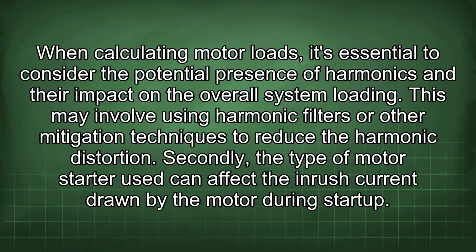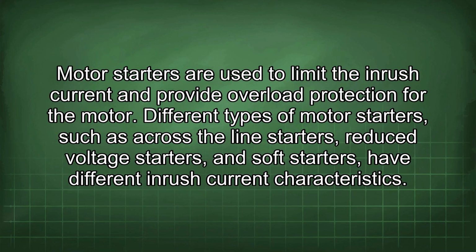Secondly, the type of motor starter used can affect the inrush current drawn by the motor during startup. Motor starters are used to limit the inrush current and provide overload protection for the motor. Different types of motor starters, such as across-the-line starters, reduced voltage starters, and soft starters, have different inrush current characteristics.